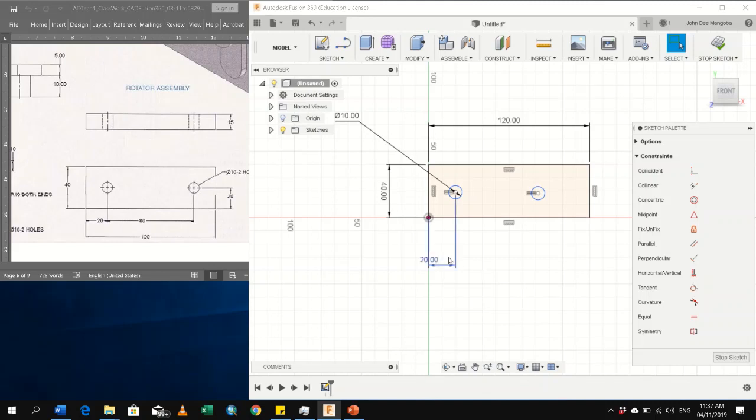We still have something missing, the dimension constraint with regards to horizontal distance. For the left side, it's also 20. In this case, we can see from the original figure that the center should be 80 units away from each other.